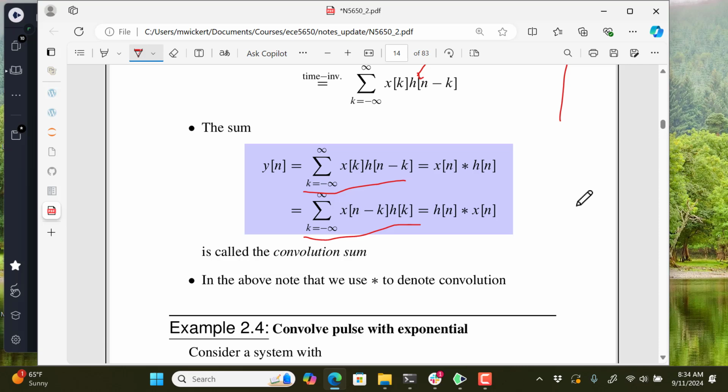And those are just a couple of pages away from here, and that's an algorithm, okay? So think algorithms in DSP at all times, because that's how we make things buildable. I mean, that's how we actually implement them. We have an algorithm to do something. The mathematical concept might be the difference equation, and what we are doing abstractly in a math sense when we apply an input to a system and we have its impulse response, we're doing this convolution sum.